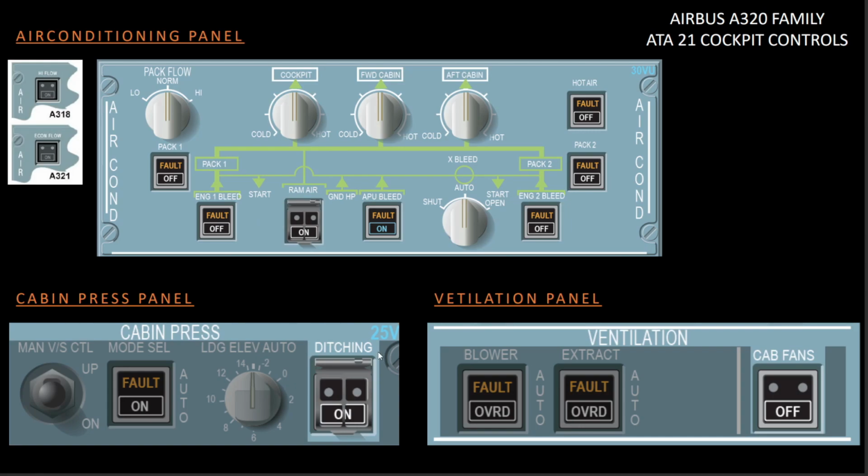If you can remember, I told you that day, the air flow will not come through the ram air inlet unless the differential pressure is less than 1 psi. So that flap is rated for 1 psi, right?